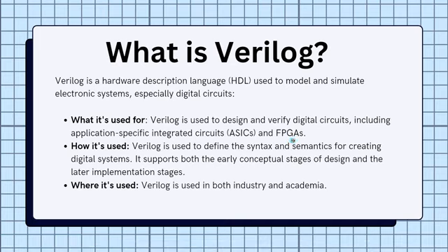Now what are the key differences between VHDL and Verilog? First of all, the purpose: VHDL was written as a description language, while Verilog was written as a hardware modeling language. Also, the main key difference is that VHDL has a non-C-like syntax while Verilog is similar to C code, and the data types of VHDL are complex while Verilog has simple data types.